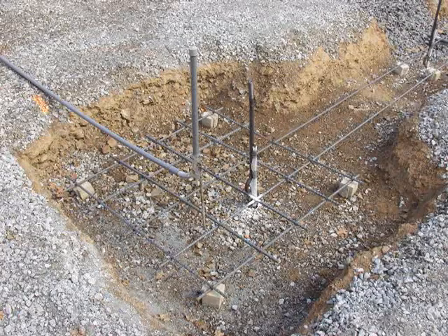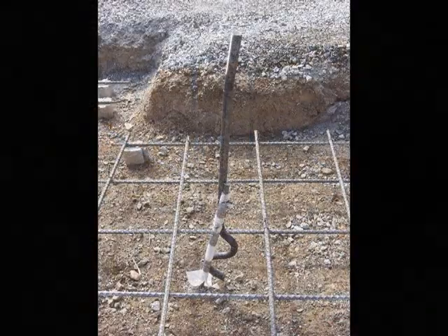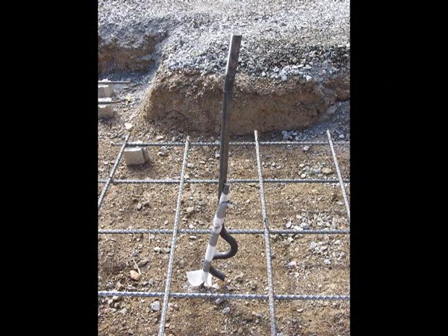One of the most difficult things about large slabs is having to place anchor bolts in the middle of the field. With nothing to support them, it's hard to get them to stay in place while you do the pour. One way to fix this problem is to drive a piece of rebar down into the ground and then attach the anchor bolt to that piece of rebar.